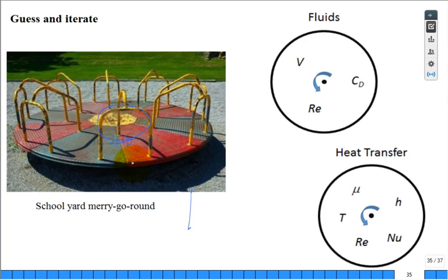This is fluid mechanics. Professor, I need to get C sub D, I need to get the Reynolds number. Pick one. You'll get better at finding the gap. For that problem, that's the one to pick because it's kind of flat. And then you'll calculate the V, then you can get the Reynolds number, then update the C sub D, and you can do this again and again, but you're going to quickly see that in one or two iterations, you're done, it's converged.